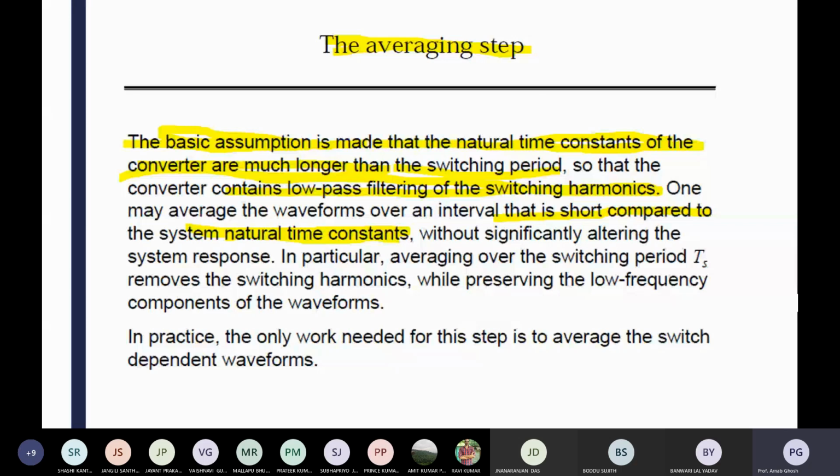Okay, so what will be the problem? Suddenly the converter comes to an unstable condition, or you can say there is observation of some instabilities. Because of what? The trajectory boundary. The converter is jumping from on state to off state conditions, and there is some trajectory boundary. If the trajectory path goes beyond your considered boundary, then the converter goes directly to unstable conditions.